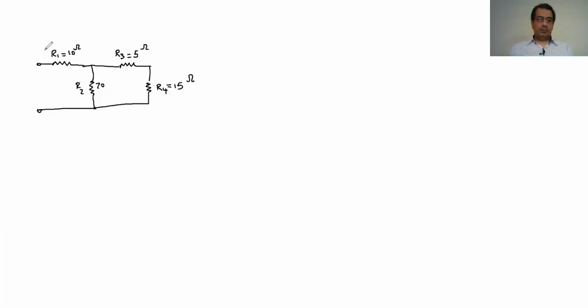If I look at this resistor with respect to any of the others, it's neither parallel nor in series, so I can't do anything with this one. The same here, if I only look at this one, again, it's not in parallel with any of the others because this end is here, but the other end doesn't connect to that, and it's not in series because it's not going end to end with any of the others.